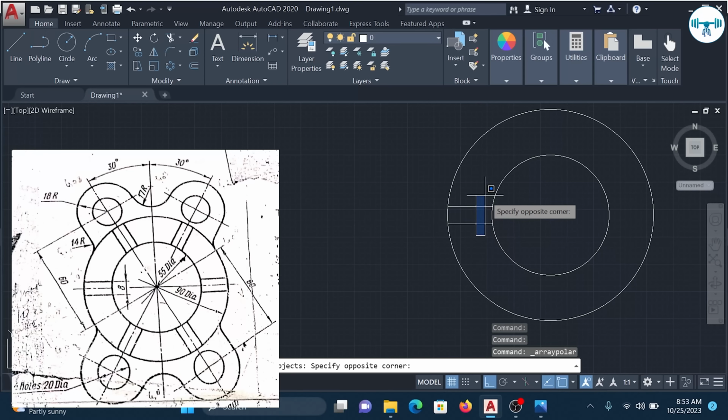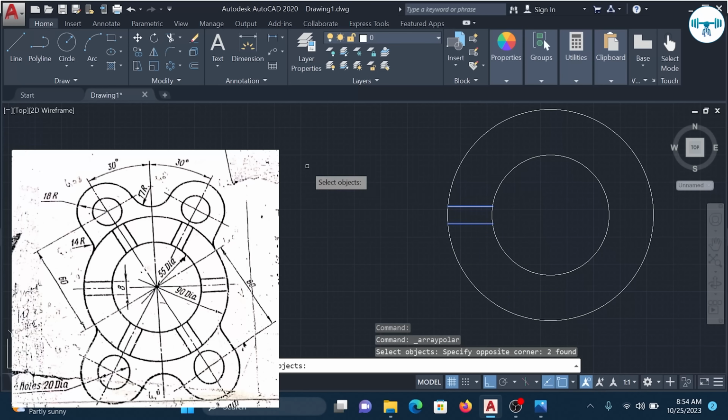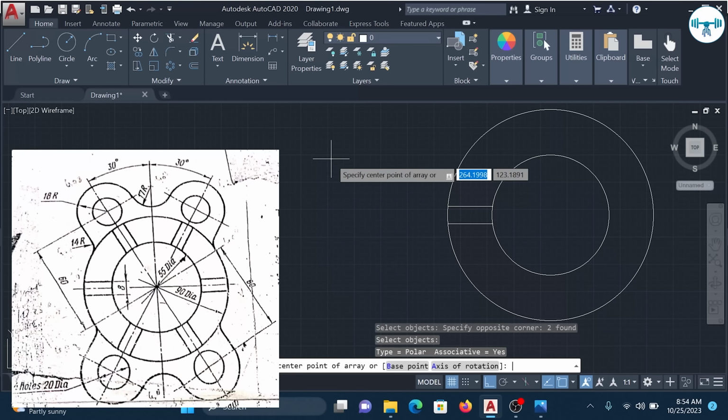Now I don't know if you have noticed, anytime I'm doing my selection, I click and then I drag leftwards. Now I clicked. If I drag towards my right, look at the shape. It's going to give me a blue color, and then with solid edges. When I drag this way, it's going to give me green color with broken lines as the edges, and that's the selection. So whenever we are selecting, you click, move towards your left to select the object. So I've done the selection and enter. Remember, whenever you make a selection, enter.